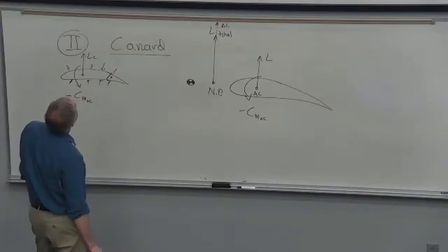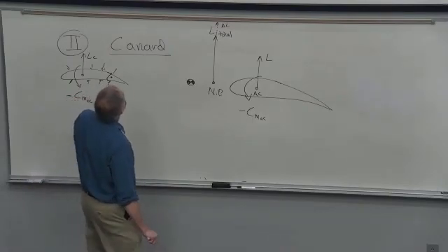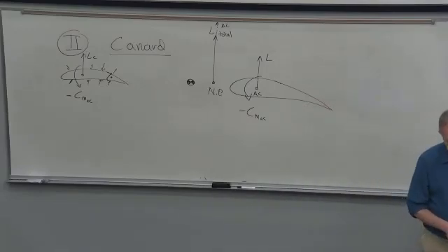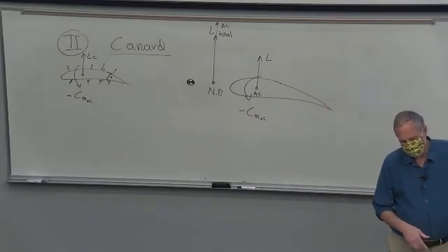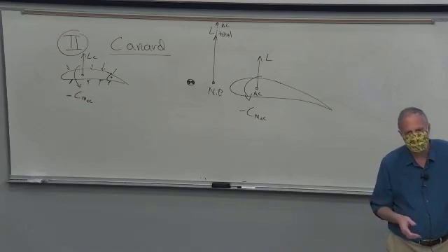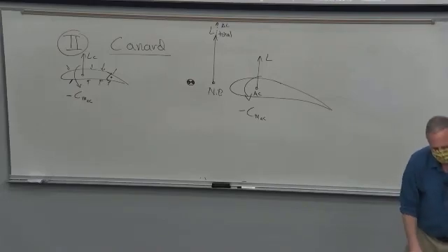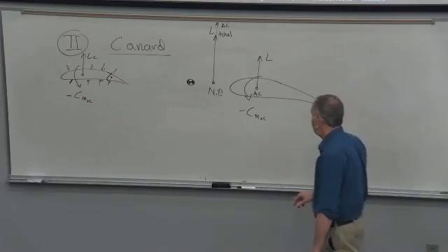I don't know about the comment about turning without the elevator because the elevator doesn't turn. Yeah, the ailerons bank the aircraft. Now, when you go into a turn and you start pulling G's, you have to add some aileron to keep you in the turn to pull the G's, but that's a different story. Oh, I talk about the vertical stabilizer. Yeah, don't worry. Ask questions. We'll figure it out.